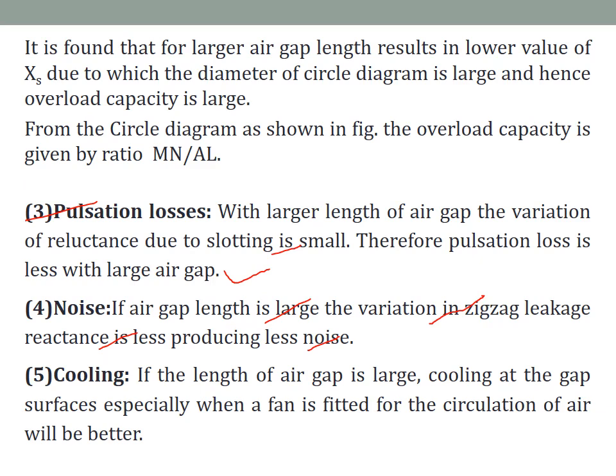Now coming to cooling. If the air gap length is large, cooling at the gap surfaces, especially when a fan is fitted for the circulation of air, is better. Cooling air passes through that air gap, and through it the heat is extracted. The cooling effect will be better.